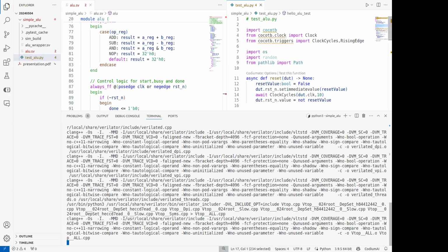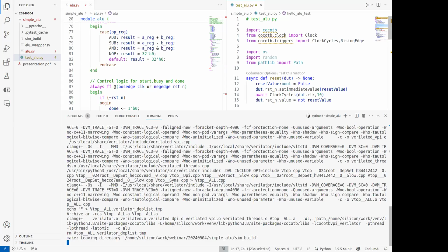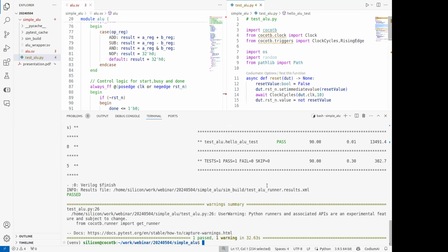Earlier I used the Icarus tool to run this, but sometimes some SystemVerilog constructs are not supported by Icarus. So I moved to Verilator, which is also open source. But both have their own limitations. You cannot run UVM test benches with these tools. You have to go for proprietary tools like VCS or Questa. But usually it's a good idea to use the open source tool for this kind of thing. So far I think syntax and other things are correct.